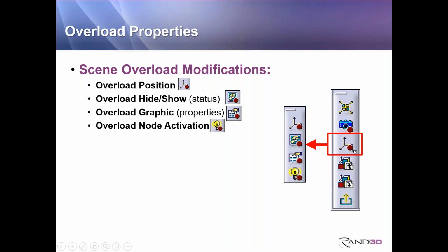Okay, when you're building your scene, this enhanced scenes toolbar will appear. And right here, if you hit the flyout, you'll be able to see those 4 buttons and choose to record those settings if you wish. In fact, this only shows up for partial scenes. Remember, partial scenes do not record anything by default, so now we're telling it to record those settings. If you're using a full scene, this is all grayed out because it's automatically recording all these settings. It's not going to ask you to hit record. It's doing it for you.